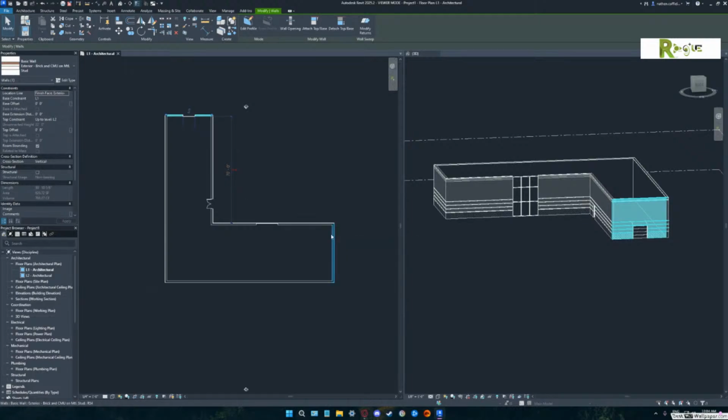Hover. Now, if you're right there and you hit Tab, it's going to select those top 2 walls. But if you slide past the halfway point to the lower half of that wall and hit Tab, it's going to select the other 2 walls. It's connecting the 2 walls together. So hit Tab and you'll see what it does. You see how that's selected? That's real important, that selection method.